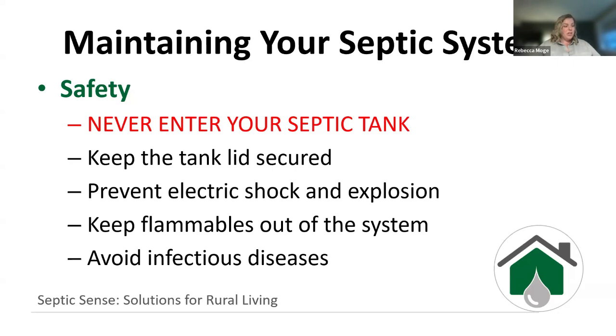Ensure that the lid is secured. If it's not a concrete lid, the lid needs to be screwed down and secured. If not, it creates a very big risk and danger, and people have died simply from the lid not being secured and falling into a septic tank. So we want to maintain that.